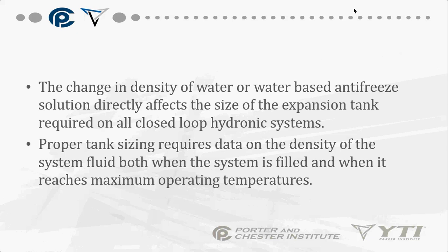Now, commercial, you could probably be talking 20, 30, 40, 50 gallons of water, if not more. You're using a bigger volume of water, and obviously it's a bigger system. It's probably going to be more susceptible to a pipe rupture, pipe freezing. So you're going to have an antifreeze glycol solution in there, so it will affect the size of your expansion tank and overall operation of the boiler.